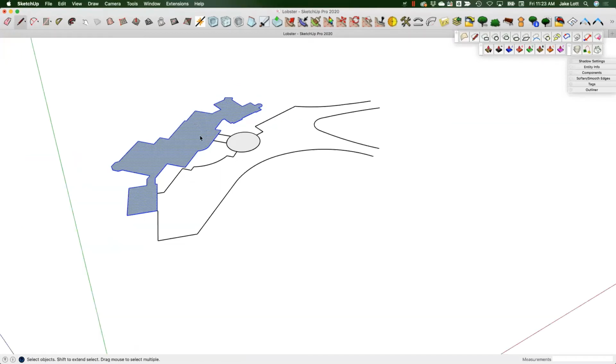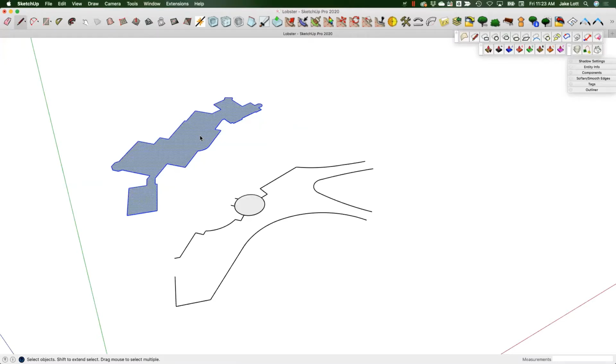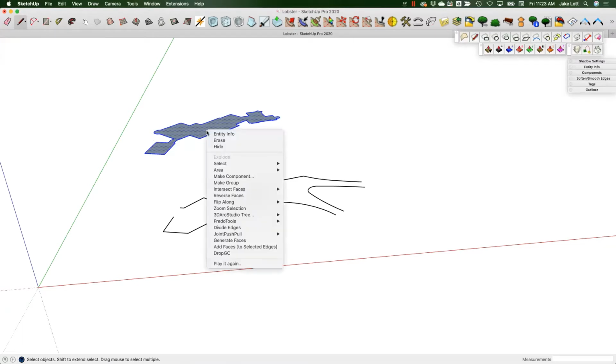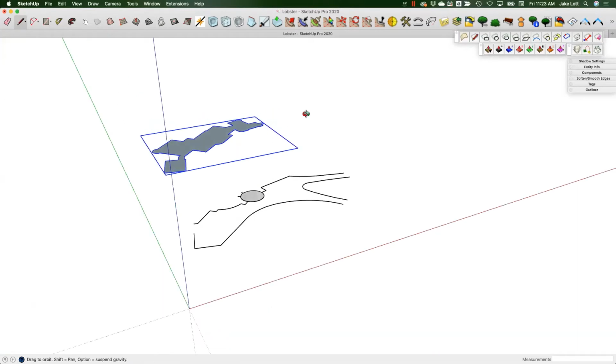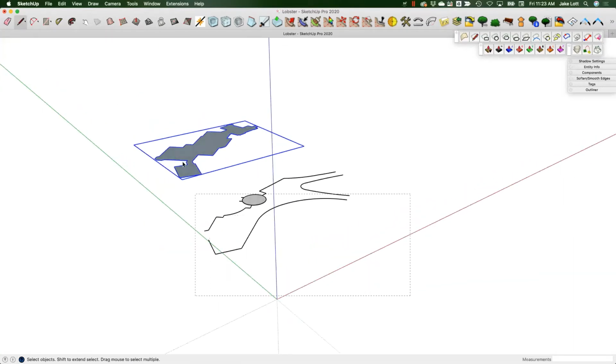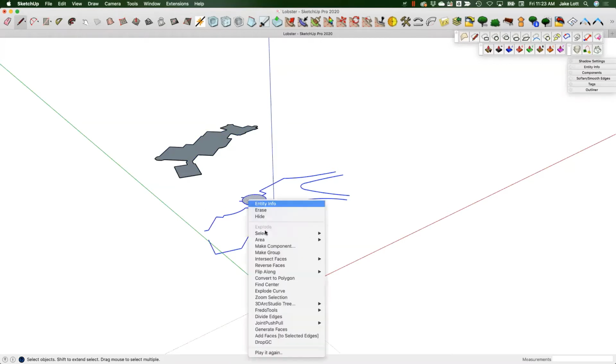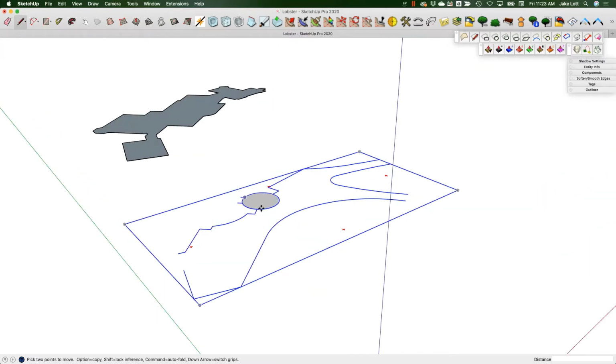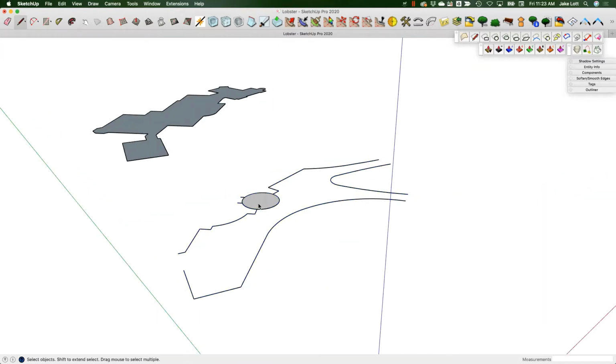So however you bring in the line work, you should always, all things considered, and this obviously has a caveat, make things into their own separate groups, okay? Because not only is it easier to select and drag over stuff even if it was a part of another group, but to deselect instead of clicking on each individual line, you can be a little less careful with what you're moving at the same time.